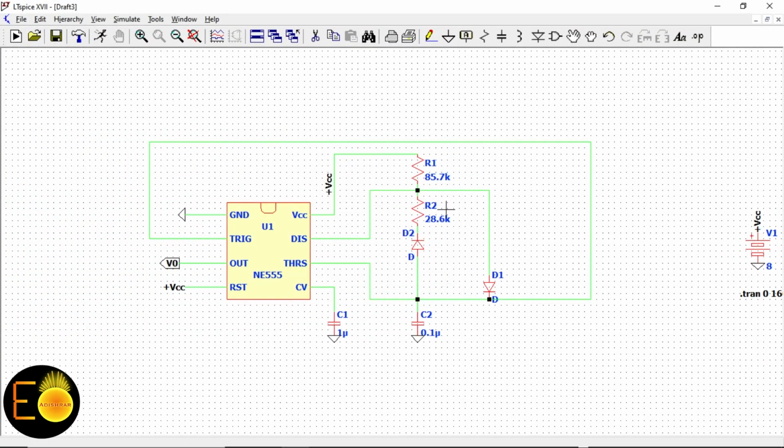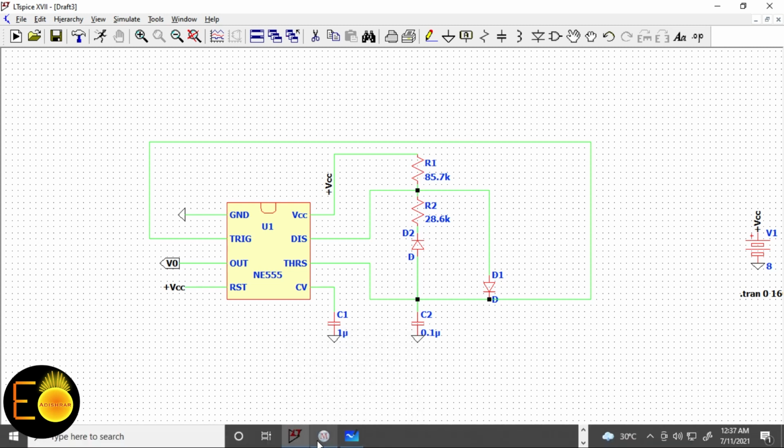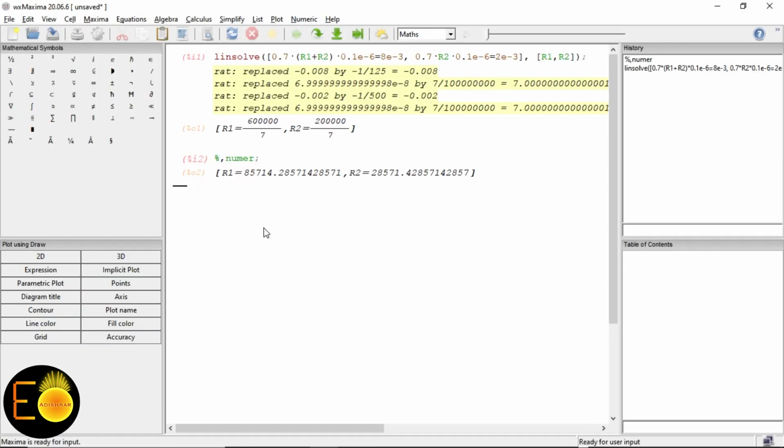Now I can make a little calculation, because every time the current is going to encounter only one resistor. So if right now I want to make my total time period 10 millisecond, then 0.7 times R times C equals 5 millisecond for one half.